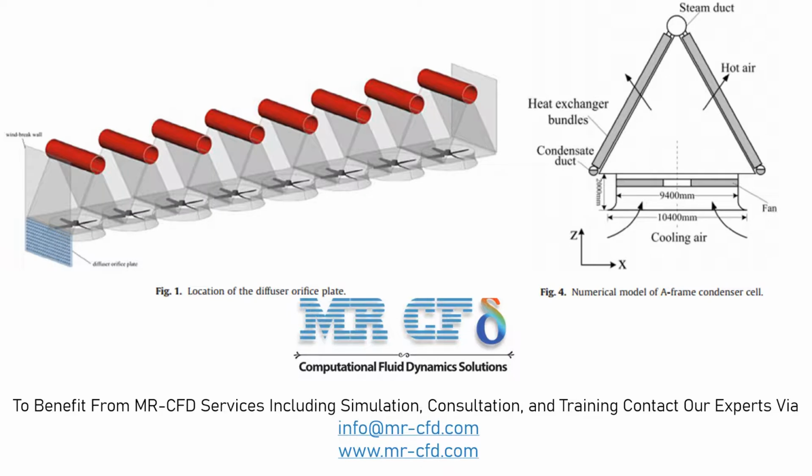Each of these rows of ACSC systems consists of 8 fans, and each of these fans is located under 2 diagonal porous plates. The operation of these systems is such that the hot and low pressure steam of turbine outlet passes through each of the pipes and then is transferred into the interior space of diagonal plates installed on both sides of that pipe. The underside of the pipe and the interior of the diagonal plates have a porous structure because the use of porous medium increases the contact level between hot steam and the cooling fluid. As a result, the heat transfer is increased and the condensation phenomenon is amplified.